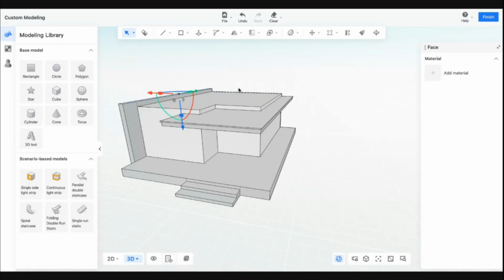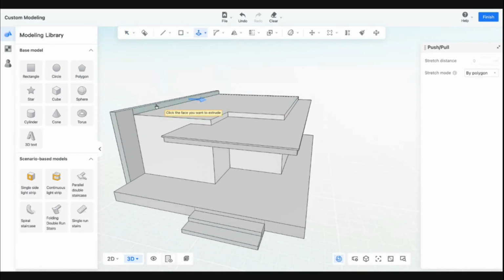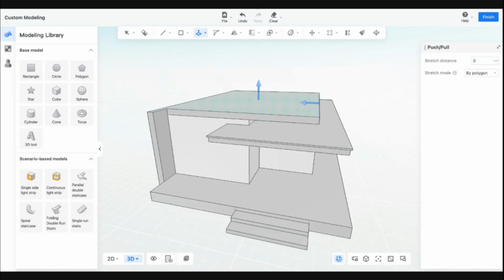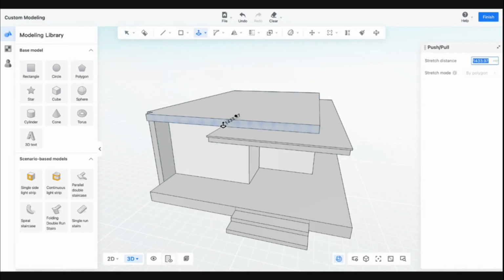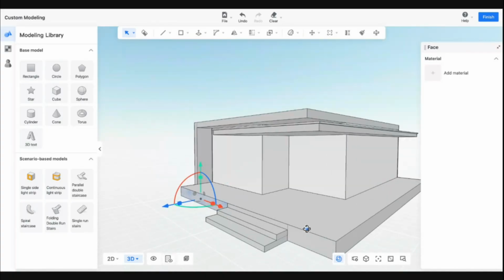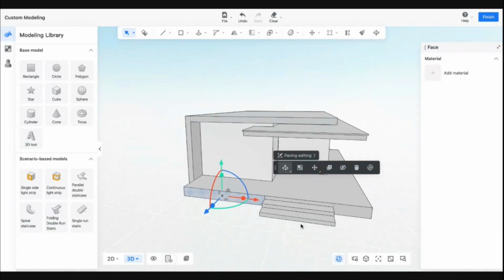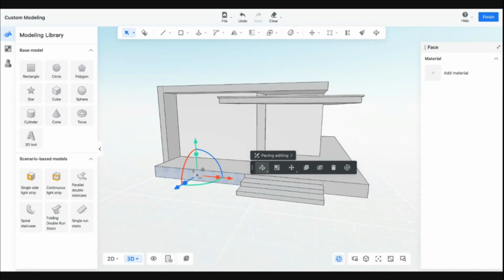Okay. And then after you're done, you add these sections to this line, right? And then they also make a gap here, so make sure you add here 1 meter, like this one. So here basically you have everything for the structures for the custom modeling of the building now.